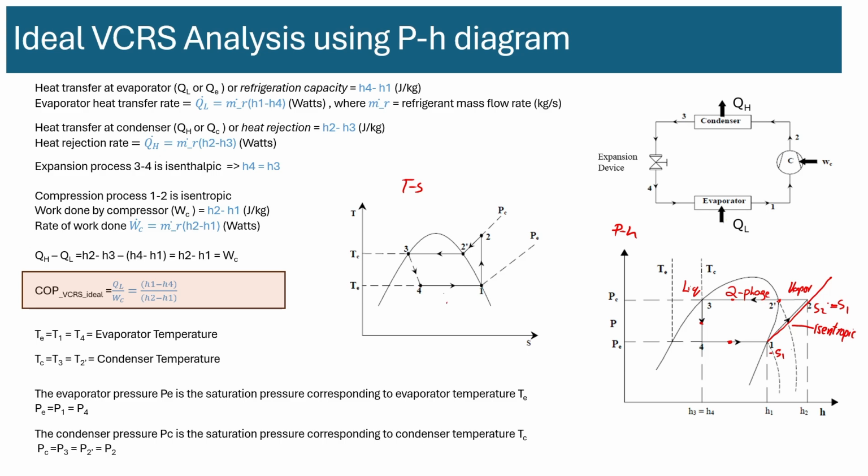So after it reaches the point 2 prime, if you cool further in the condenser, right? First of all, you're reducing temperature because you're cooling the condenser, and you can cool it using water or air or by direct contact with a colder substance, right? So in our lab, we are using a water-cooled condenser. Now, when you cool the condenser, its enthalpy keeps dropping from H2 all the way to H2 prime and then all the way down to H3, right?